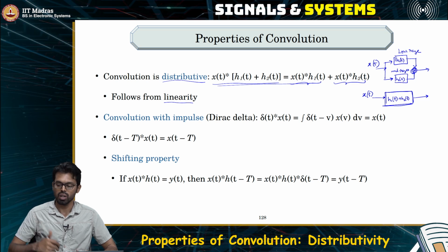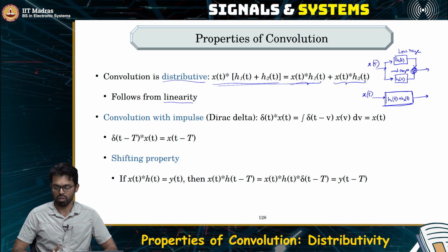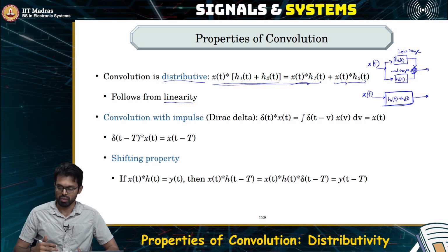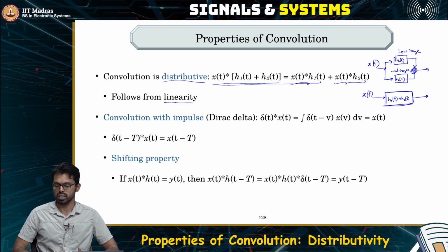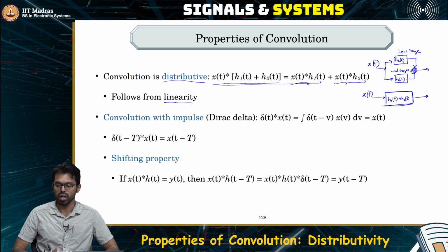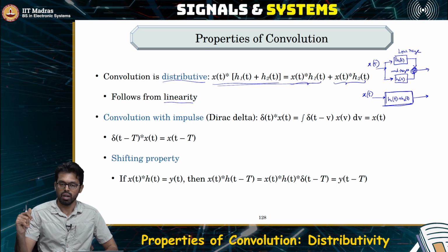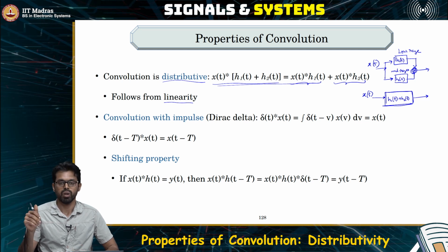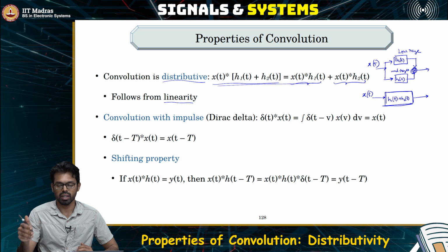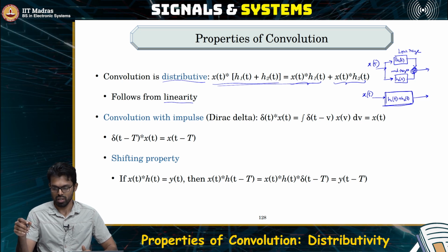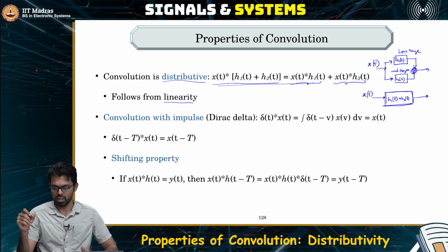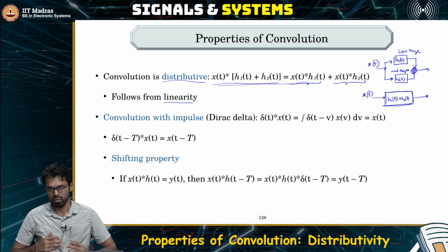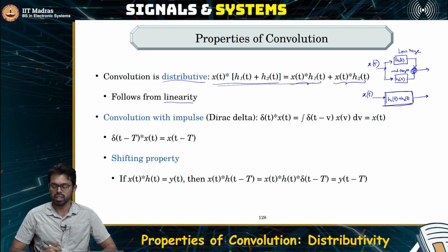So the low range would increase the bass of the audio and the high range would increase the volume of the high frequencies such as percussion instruments and so on. So what we are doing in that particular case is exactly corresponding to this scenario. This is an analytical expression of the case which is very similar to the audio equalizer, where we give the same input to multiple filters which have different gains and then finally add them together.